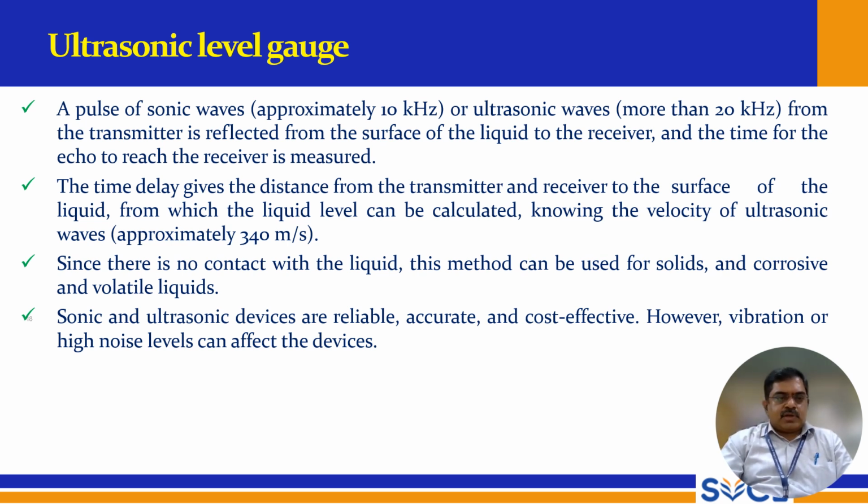So a pulse of sonic waves, approximately 10 kilohertz, or ultrasonic waves of more than 20 kilohertz, from the transmitter is reflected from the surface of the liquid to the receiver, and the time for the echo to reach the receiver is measured. The time delay gives the distance from the transmitter and receiver to the surface of the liquid, from which the liquid level can be calculated, knowing the velocity of the waves, approximately 340 meters per second.